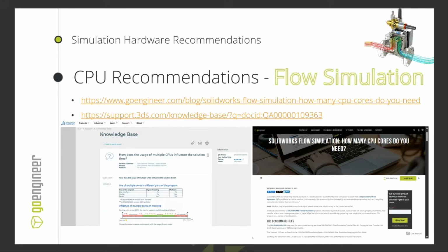So it has to do with how efficient a solver is at threading the processes out, and that means splitting out the job to populate those cores. And 64 cores for SolidWorks simulation, you're going to get zero benefit from that. In fact, I think what you'll end up finding is it's actually slower than trying to force simulation onto fewer cores, just because it's not as multi-thread capable.